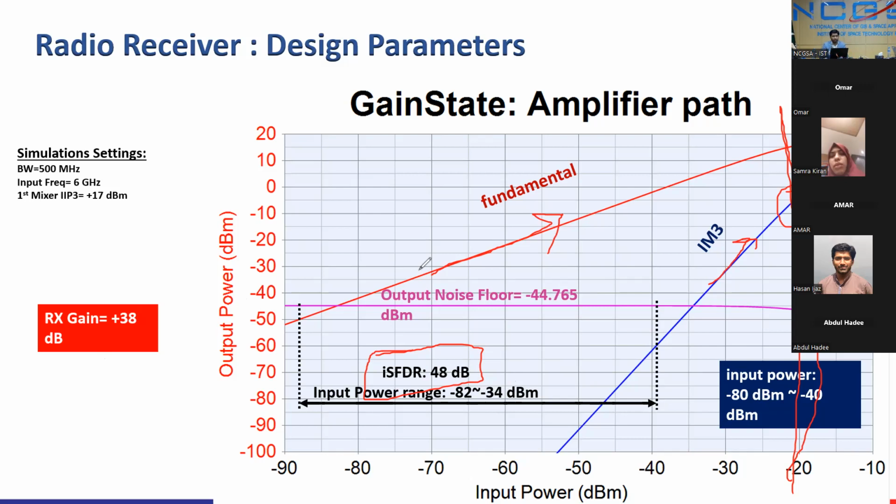Usual ADCs, I'm repeating again, if it is a good ADC, the noise floor of the receiver will be around minus 60 dBm. It cannot see below that. Now, if you want to detect a signal of maybe minus 80 dBm or minus 70 dBm power, you need to increase that to come into the range of the ADC. So that is actually the significance of this plot.